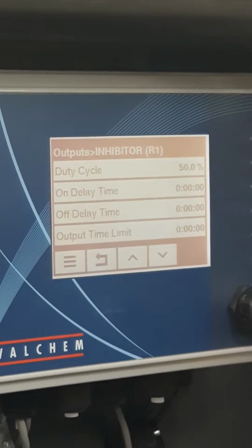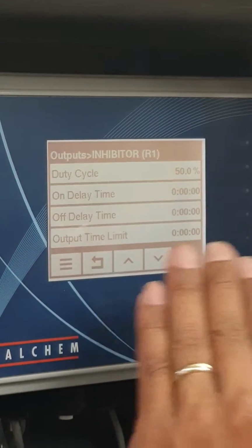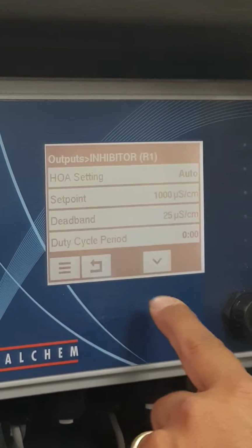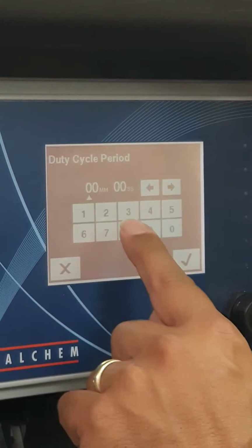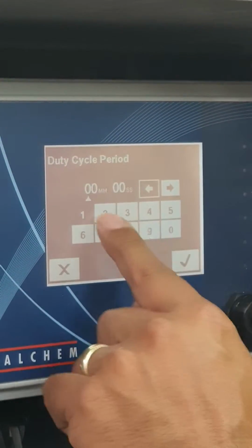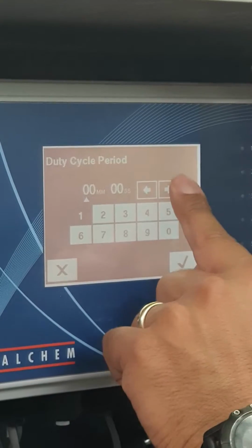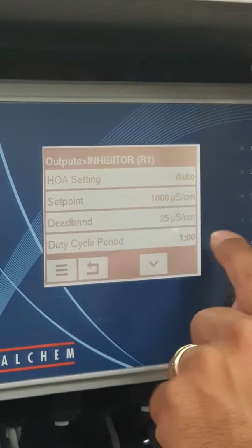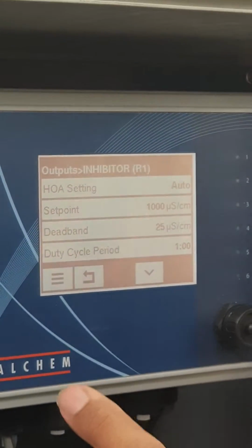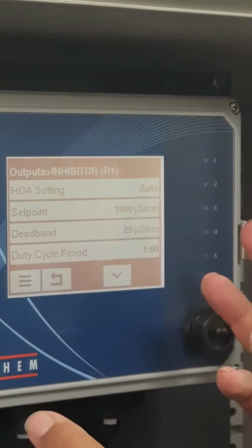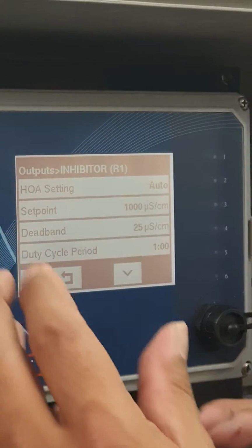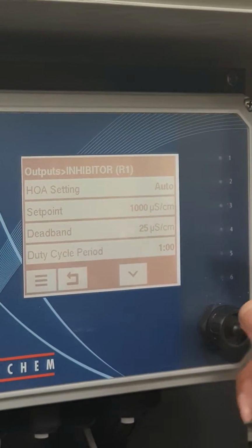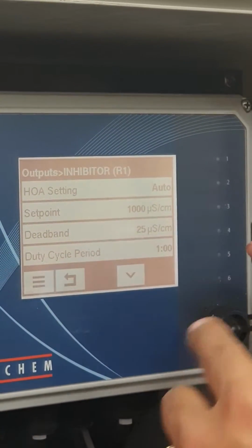You might ask yourself, why the heck do that? What it does is this creates really fine control. So when this is activated and going, every minute, oh, that's an hour, go back, whatever. Boom, there we go. What it would say here is every minute it's going to do this, but for 50% of that, or 30 seconds of that, it's going to monitor, and 30 seconds it's not. And then another minute it's going to look at it again, but 30 seconds it will actually monitor and do something, and activate a relay if it needs to, and 30 seconds it won't.